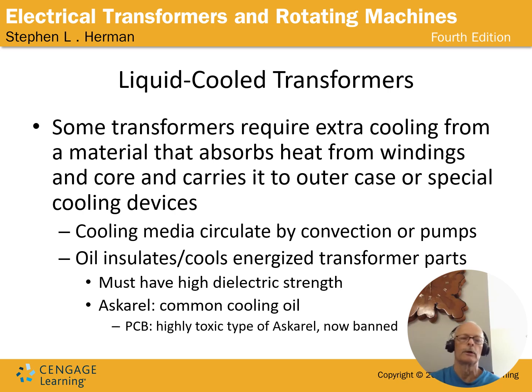When you mess with this stuff, you need to check the SDS and make sure you're wearing the proper PPE, so that if you get any of this on you, you get it cleaned off properly. You don't absorb those chemicals. It's very, very toxic. PCBs were banned to a large extent, I think pretty much totally, back in the 70s, but there's still some around.